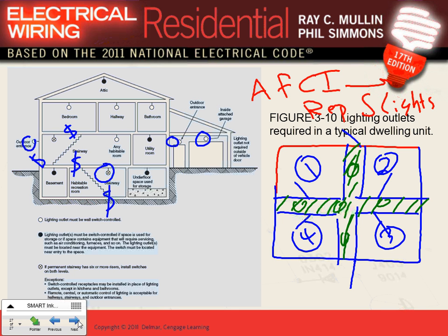Now, in terms of safety, the arc fault circuit interrupter is supposed to monitor the circuit, everything in the circuit, the branch circuit as well as the devices. If it sees any arc, phase to phase, phase to ground, or if there's a break in the phase and it arcs, they call it series or parallel arc: series inside the line that's going in, parallel between a line and another line.